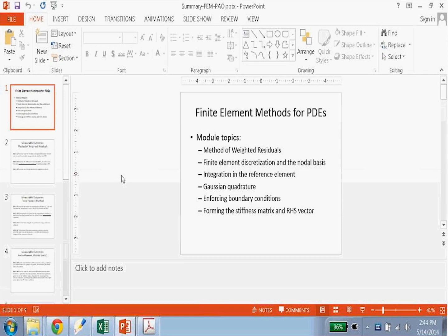If that is our governing equation, and we have an approximate solution that we call, say, T tilde of x, then the residual R is a function of that approximate solution, and also a function of x. It would be defined by bringing everything over to the left-hand side: d/dx of (K dT tilde/dx) plus Q. That is the definition of the residual, and if the approximate solution were exact, in other words, if we put not T tilde but T in here, the residual would be 0.